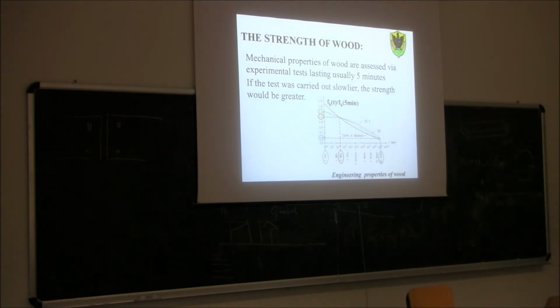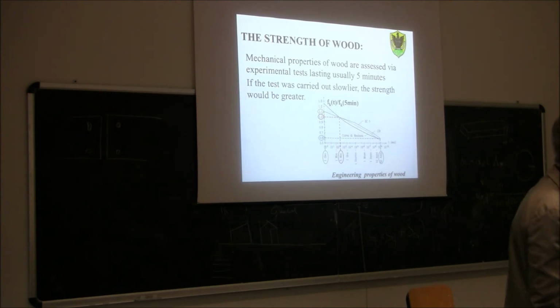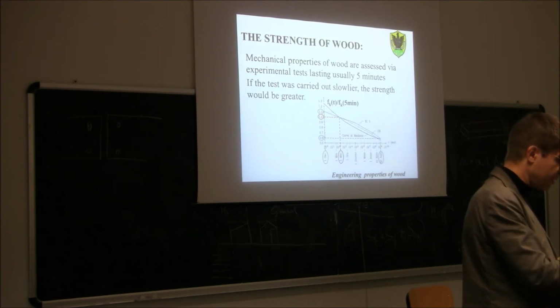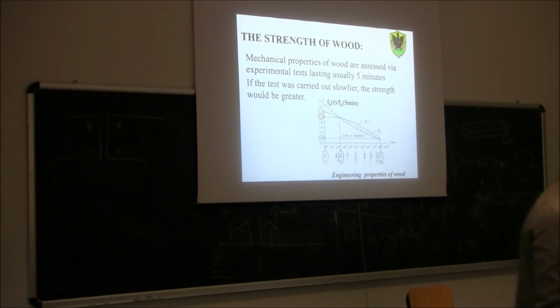Now, the question for you: why are we interested in strength values for different load durations? When you design a timber structure, why do you think it's important to know the strength for different load durations? Because of the anisotropy of the wood. No, the anisotropy was already taken into account. Not necessarily by the load duration. I mean, the anisotropy we already know, this way is better, this is worse, and so on. This ratio will be the same in all the directions.